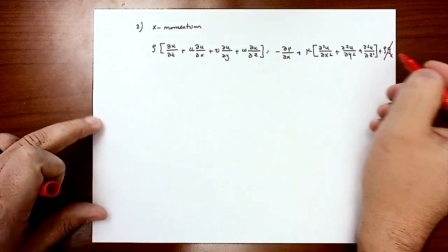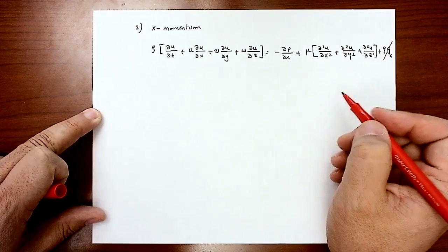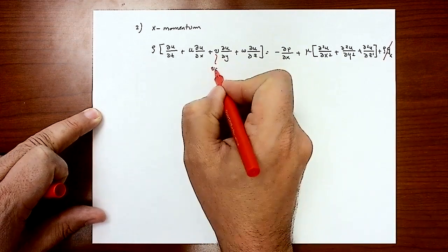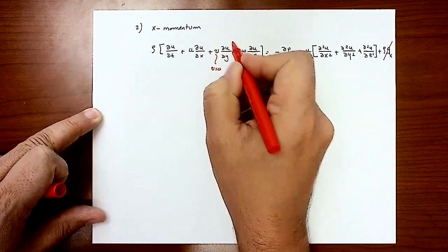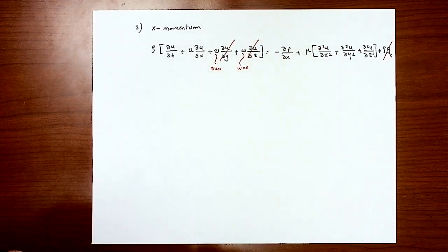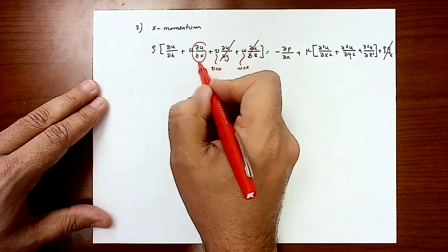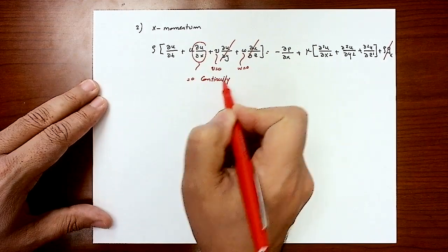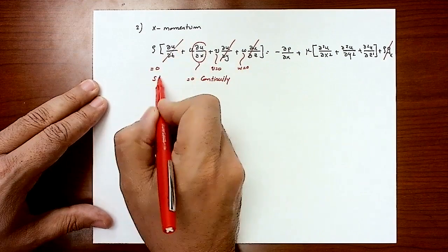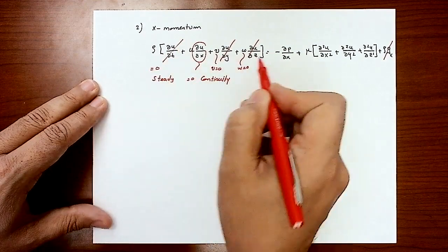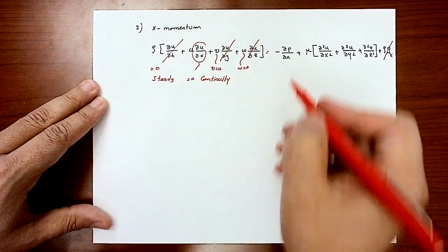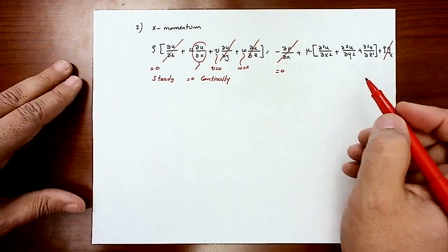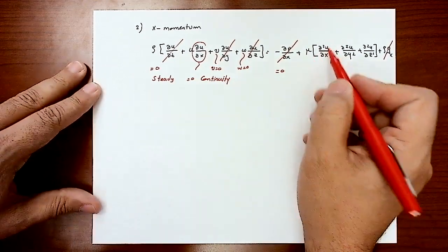Body forces are neglected since we are doing one dimension, right? So this means that v and w are 0, so v is equal to 0, w is equal to 0, so this term goes away here. Then we know that partial u by partial x is equal to 0 from the continuity equation, right? This is 0 for steady flow. So simply the left-hand side is totally 0, and there is no pressure gradient in Couette flow, so this is also 0. So I'm going to end up having only mu partial squared u by partial x squared.